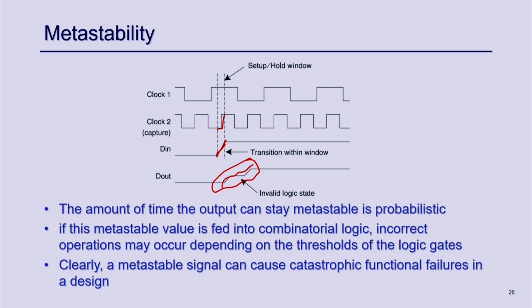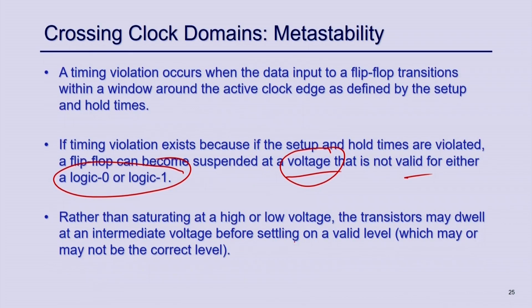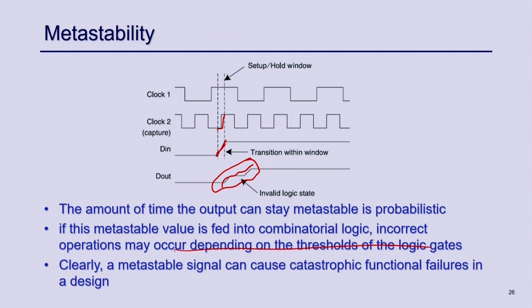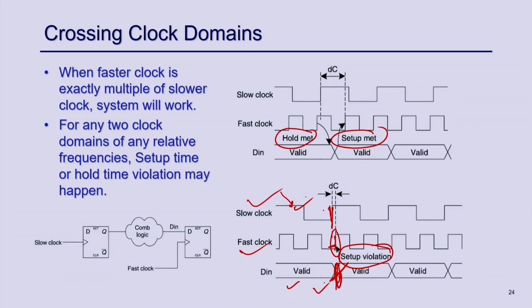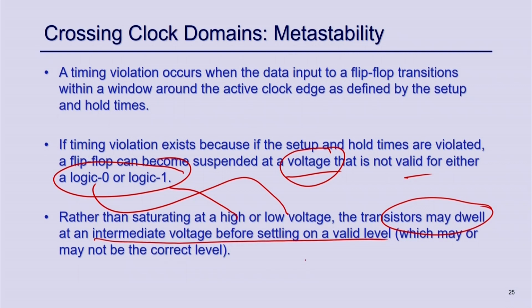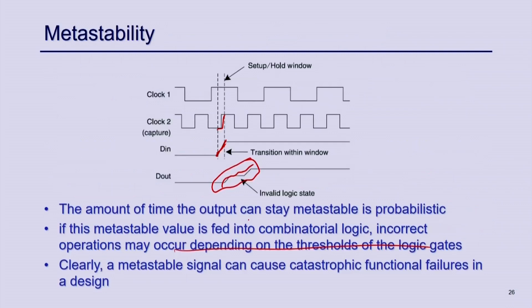And this particular metastability will go through this circuit following this, right. It will actually go through the combinational circuit, the following gates also. So, this metastability will propagate and may propagate to the output, right. High voltage means 1 and low voltage means 0, so it might dwell at some intermediate voltage, and after some time it may settle to some value, I do not know what value, some state, right.